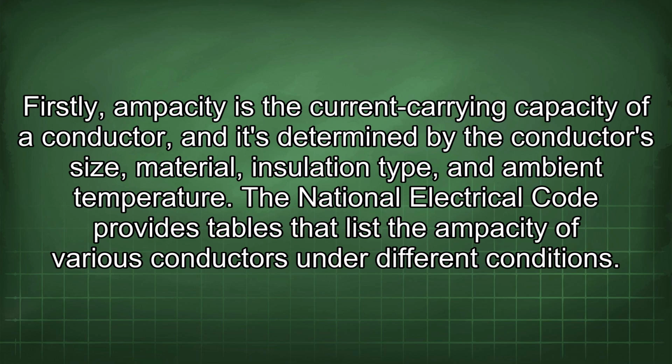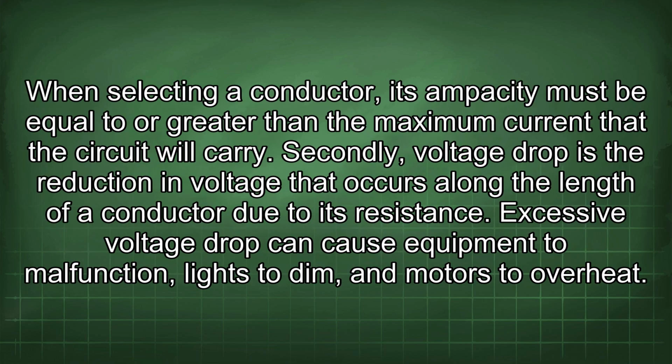The National Electrical Code provides tables that list the ampacity of various conductors under different conditions. When selecting a conductor, its ampacity must be equal to or greater than the maximum current that the circuit will carry.